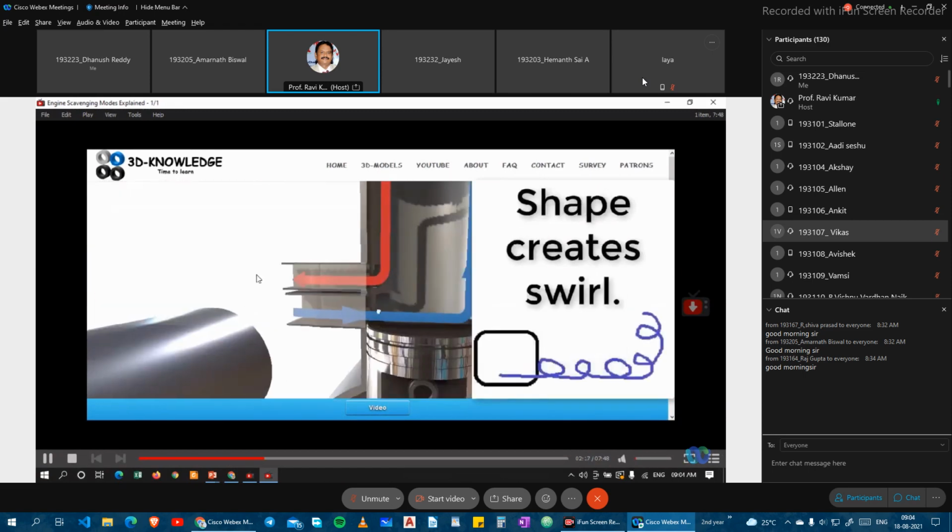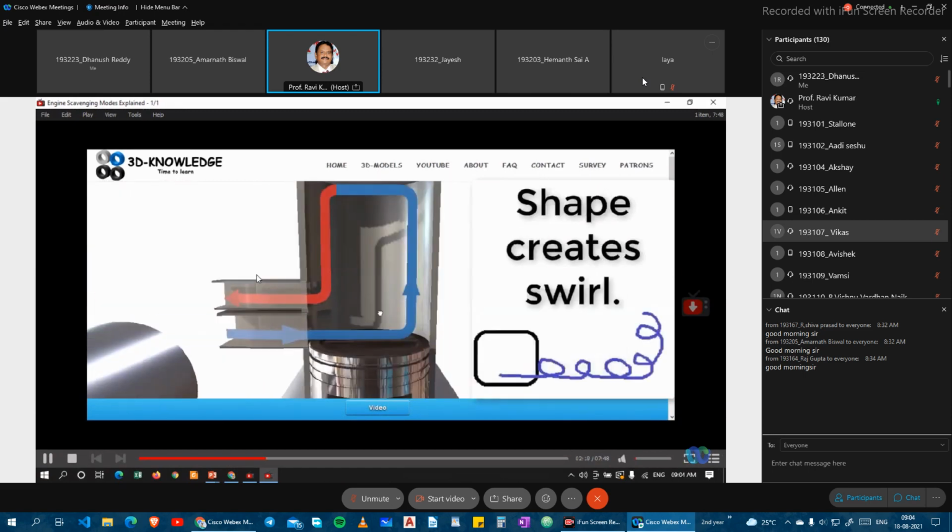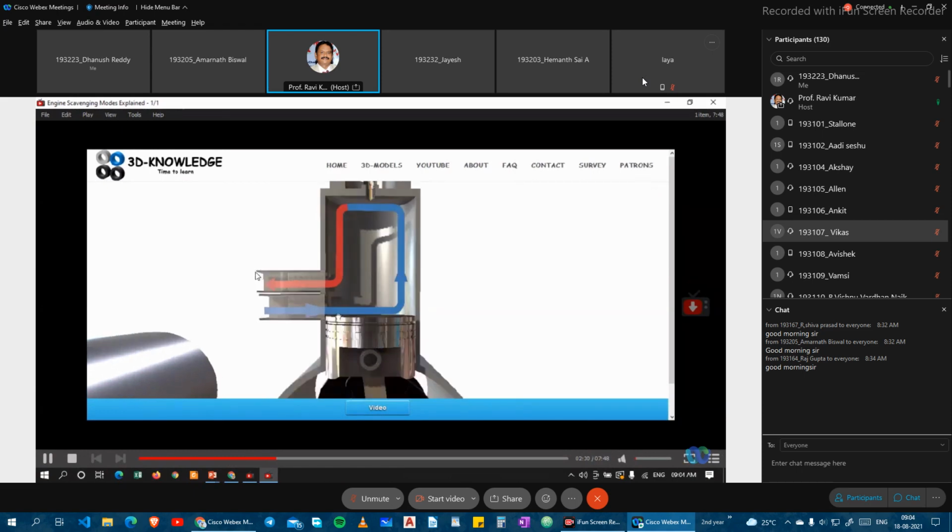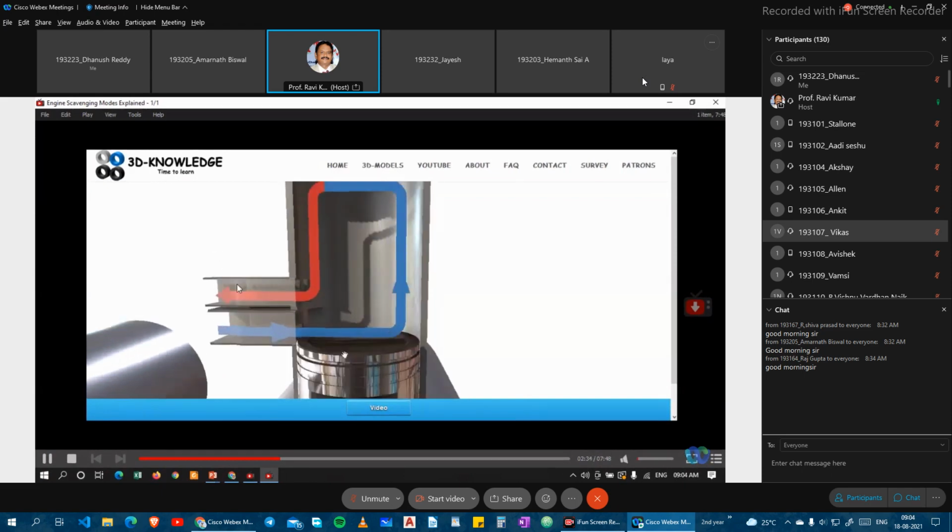This is one method where we are going to see this. This thing you basically see in a four-stroke cycle. Exhaust gases also are pushed from TDC to BDC in the exhaust operation. But here in two-stroke we cannot have a separate stroke. That's why we are going to have this arrangement, and both places, inlet and exhaust, will have separate ports arranged here.